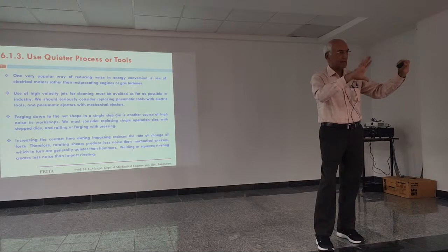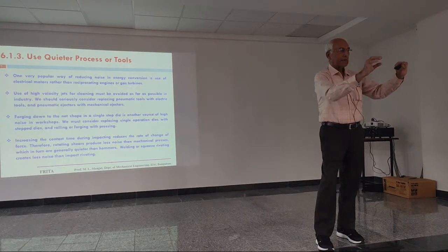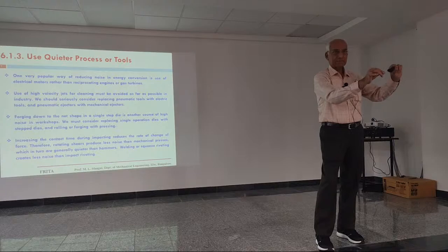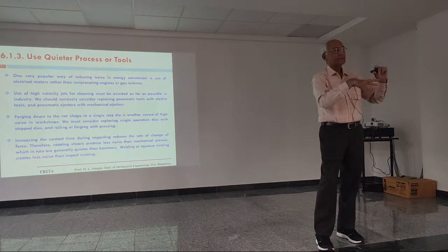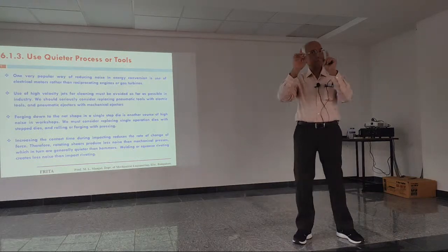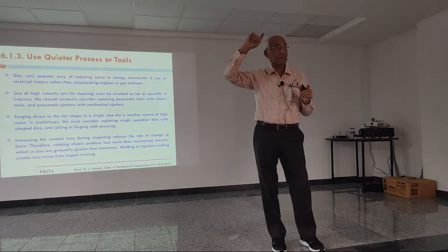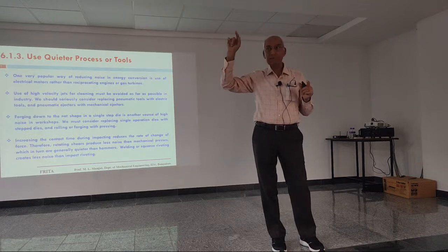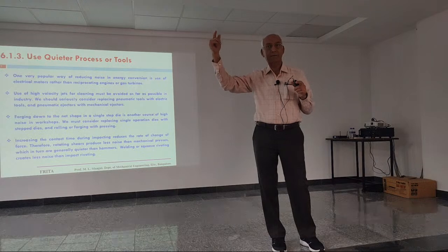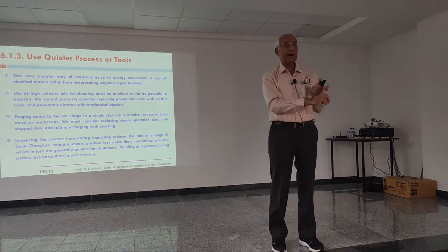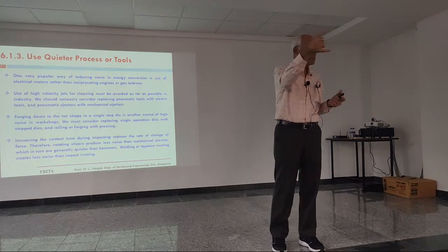So I have increased the mass now, and then velocity is decreased. Okay, and then when you find the thrust, thrust is still the same, but noise is proportional to 8th power of velocity. Noise is proportional to 8th power of velocity. So if I have made the velocity half, I am reducing the noise by 24 decibels straight away.